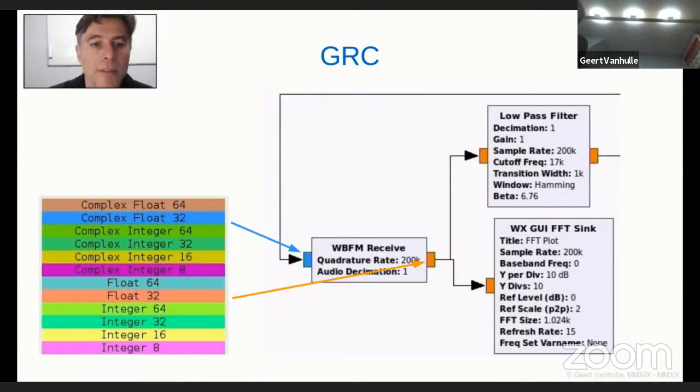So no longer a complex signal, a normal sample series, but of 32 bits float value. Now the WB-FM is a wideband FM demodulator. It's a quadrature demodulator. How it works inside would lead us too far. It's just software, mathematical representation, again, just like we discussed with some other parts before. Mathematically, you can also demodulate from this baseband 200 kilohertz the analog output signal in a digital sample representation form, of course.